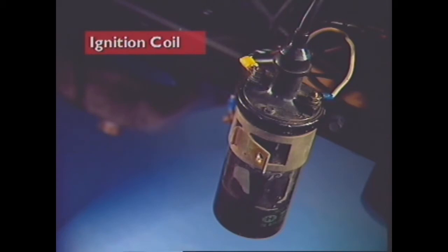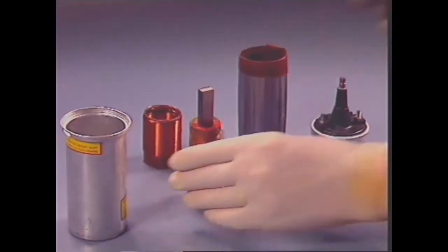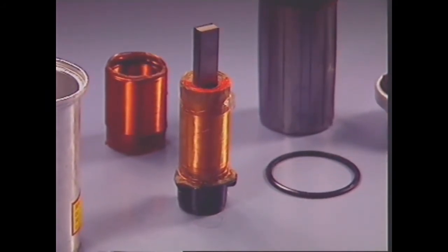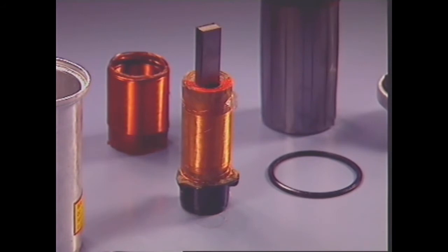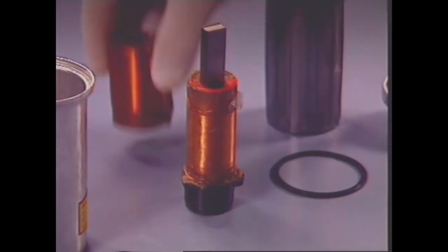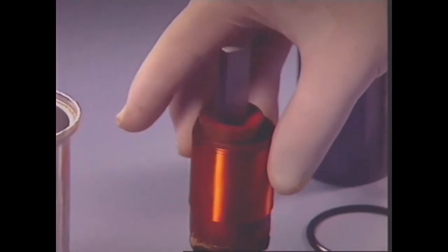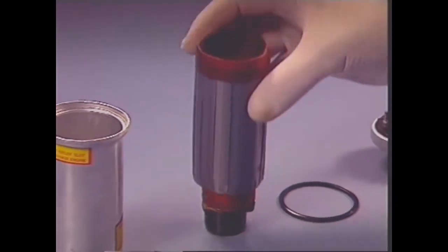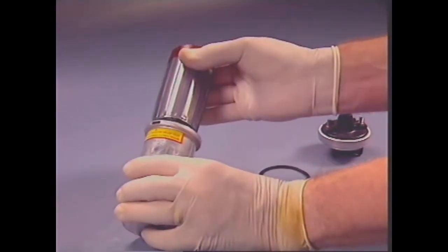The ignition coil is a step-up transformer which raises the nominal battery voltage of 12 volts up to the many thousands of volts necessary to provide a spark across the spark plug electrodes. A standard ignition coil has a rod-shaped laminated iron core, which is located centrally by an insulator at its base. The secondary winding, with 15,000 to 30,000 turns of very thin enameled copper wire, is wound around the core and is insulated from the core by layers of treated insulated paper. The primary winding, with a few hundred turns of much heavier copper wire, is wound on the outside of the secondary. A shield of soft iron surrounds the outer windings, and the complete assembly is inserted into a one-piece steel or aluminium container.